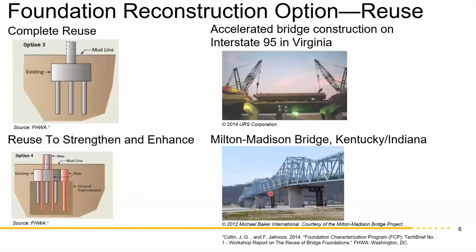Okay, so they demolished the old bridge. They brought these sections of truss bridge, put them on this temporary bridge, and put it in place all in 3 days. So the impact was only 3 days of replacement. We call that accelerated bridge construction using prefabricated elements. But the net effect of the reuse was $50 million in savings. So it was, again, quite substantive.